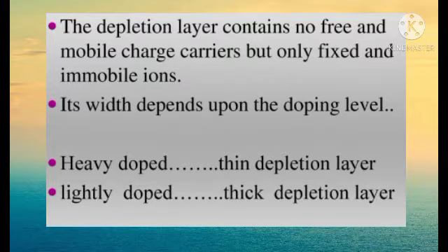The depletion layer contains no free and mobile charge carriers but only fixed and immobile ions. The width of depletion region depends upon the doping level. Heavily doped has a thin depletion layer and lightly doped has a thick depletion layer.